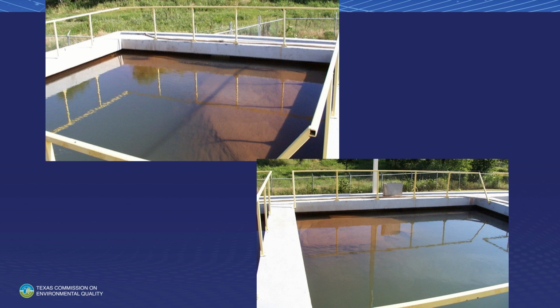This is an interesting situation. In open channel flow, and my engineer friends out here will help me, there's such a thing as what we call dynamic head inside these channels. And what that means is that water comes down that channel, the velocity of that water going through a single opening, a port, tends to drop the pressure in front of that port such that sometimes the flow through that port into a sedimentation basin is lessened to some degree.